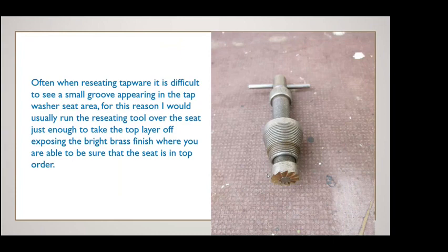I think it's good to do a disclaimer first and say, well, I will attempt to do it. I can't guarantee until I take it apart. I don't know the condition of the seat or the components, so basically let them think that it's possible you may have to replace it, but I'll try and fix it. And if I can, lucky you, sort of thing. Yeah, a reseated tap is not going to last as long as a brand new one as well.